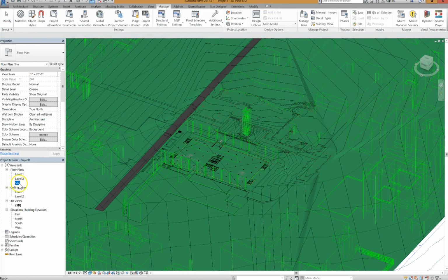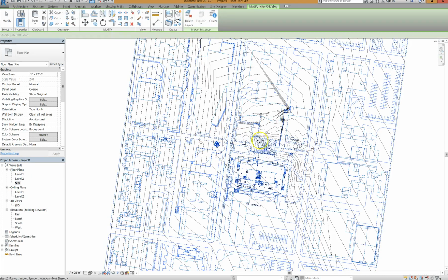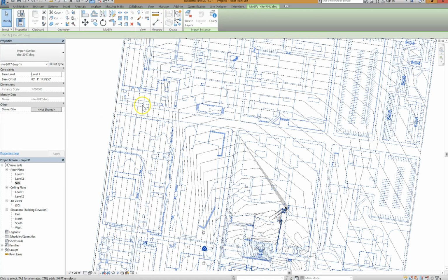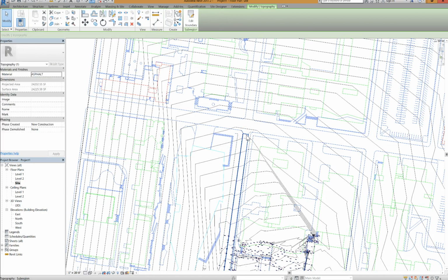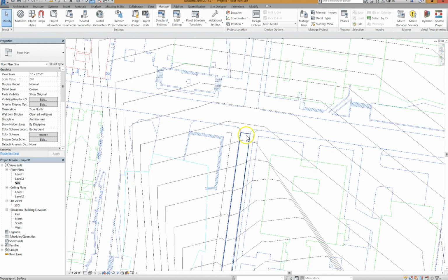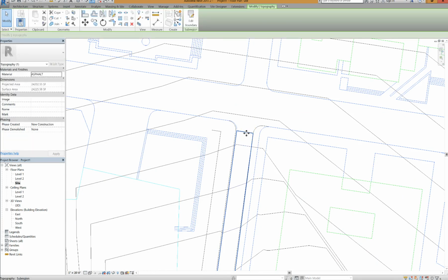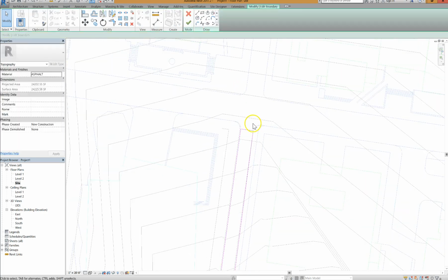So going back to site, what we might want to do is complete across some of the cross streets. And what you want to do is add on to the one you already have. If you're making a street, if we're making a sidewalk, we might want to make our own ones. So if I come over here and hover over this, if it doesn't offer it up to you, like it doesn't turn blue, you can always hit Tab until you get to it. But I'm going to click on this, hit Edit Boundary, and again that activates as being pink.